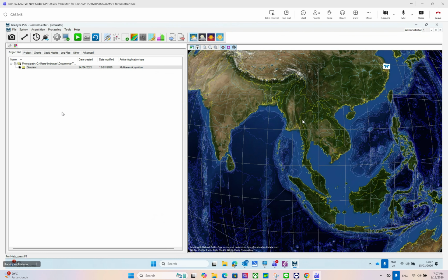And the IMU is expecting certain movement from the antenna, from the GPS position, because you gave it that lever arm, but it doesn't coincide with what the IMU is measuring, and then the IMU will say, something's wrong here. That's what the algorithm does. That's how these systems work. So, accuracy, accuracy, accuracy. I cannot emphasize that more. It is important, very important.